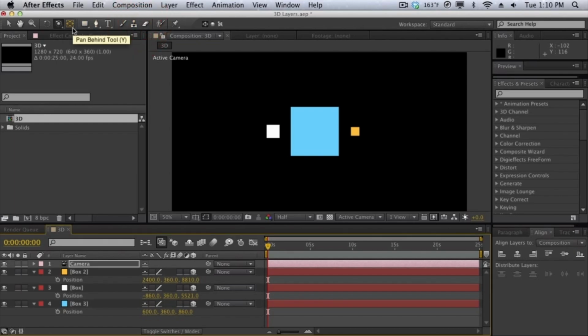So if you hit C on the keyboard, you can see that I'm navigating through the different types of camera tools here. I say 3 when there's actually 4, because the unified camera tool is pretty much the tool that has all of these combined. If you have the unified camera tool and a 3-button mouse, you can navigate through the different types of tools by clicking. For example, if I left click, I get the orbit tool. If I right click, I get the pan tool here. So the unified camera tool is all these tools combined, but I usually don't use it.